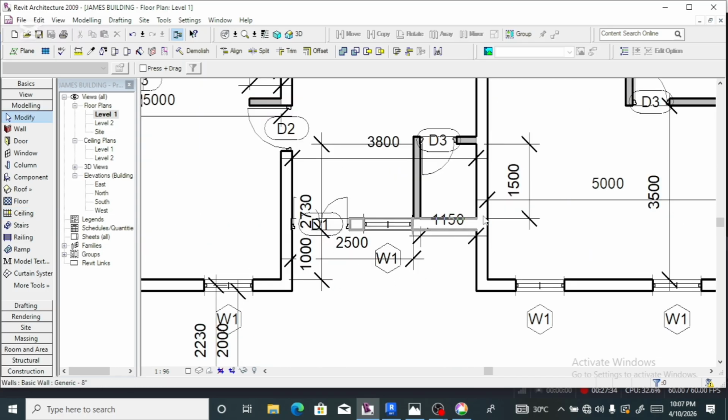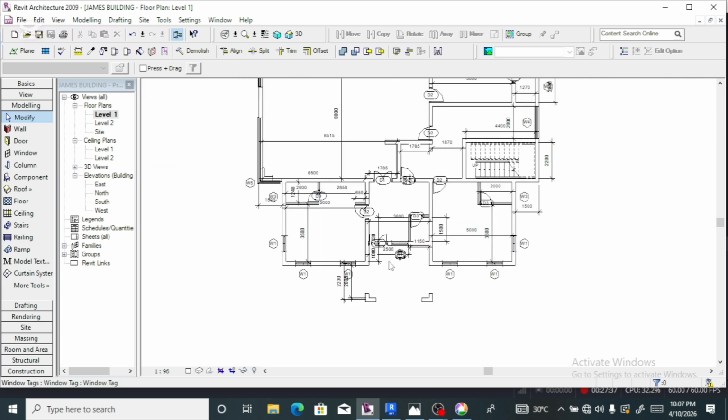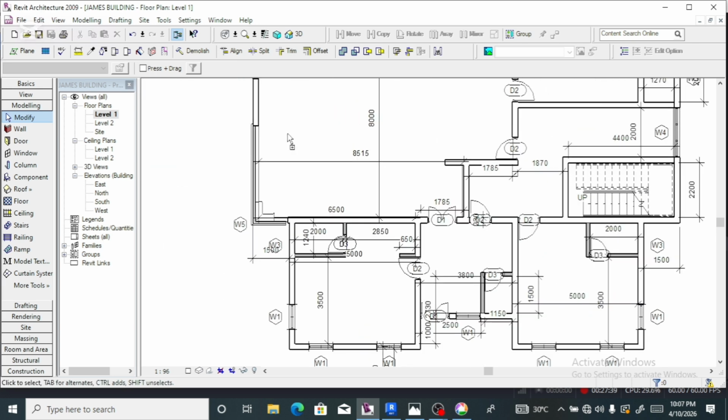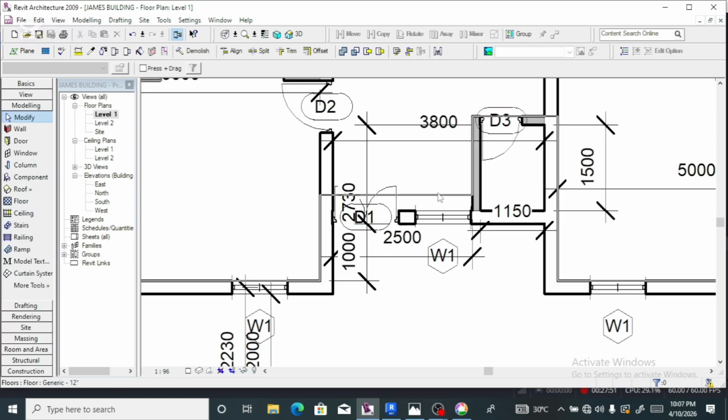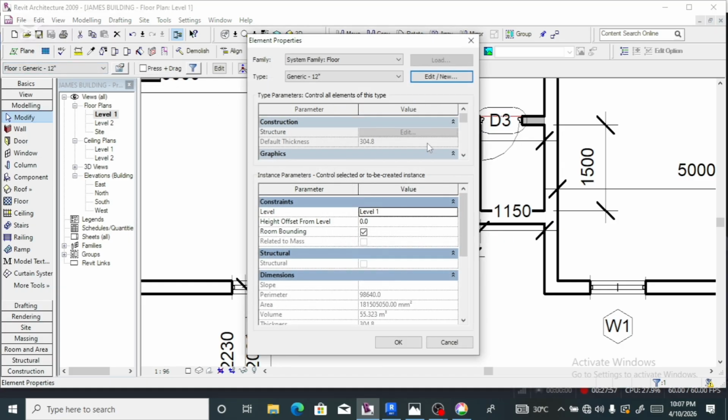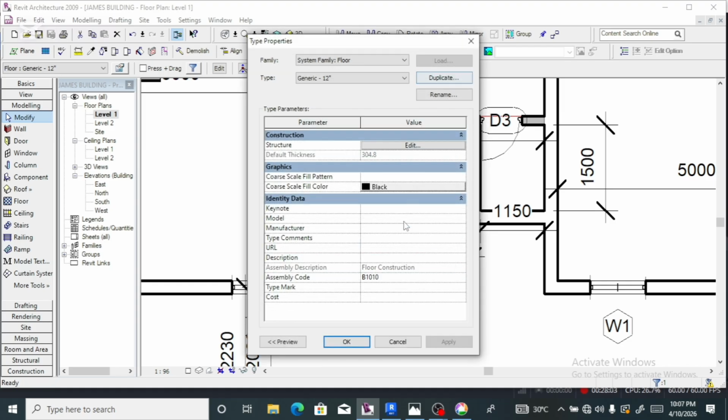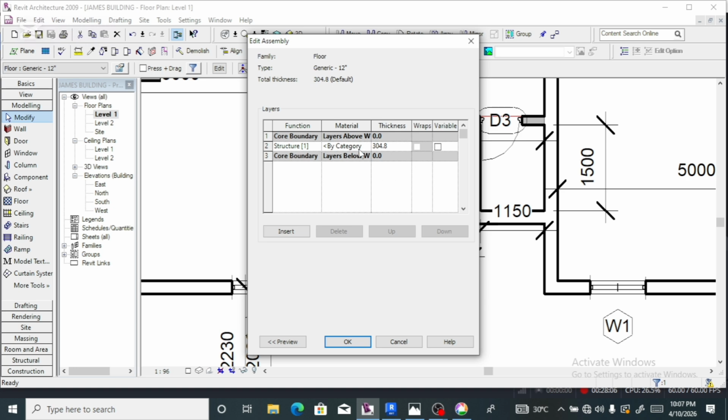Finish this. This is Control Z. I want to pick an edge where I can work with. Okay. Shifted it back. Finish. So I could use it to highlight from here so I can do some settings here. To my settings, edit from here. And the thickness, the depth of the floor should be 150.